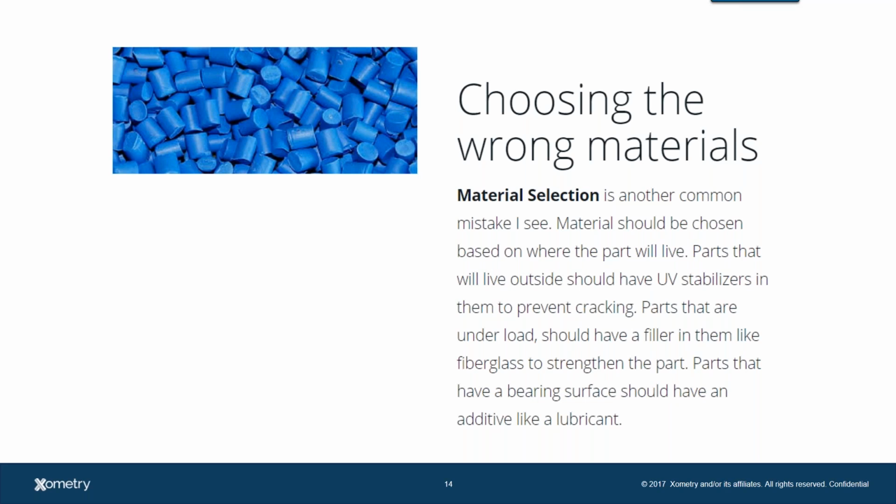Is this something in a ruggedized outdoors environment? It's going to take a beating. Maybe I use a 30% glass fill nylon. Is this part going to go hot, cold temperatures? I may use a different material. But you want to think about your application. And the biggest reason why is we are going to be designing and quoting this tool around that material that you're choosing.